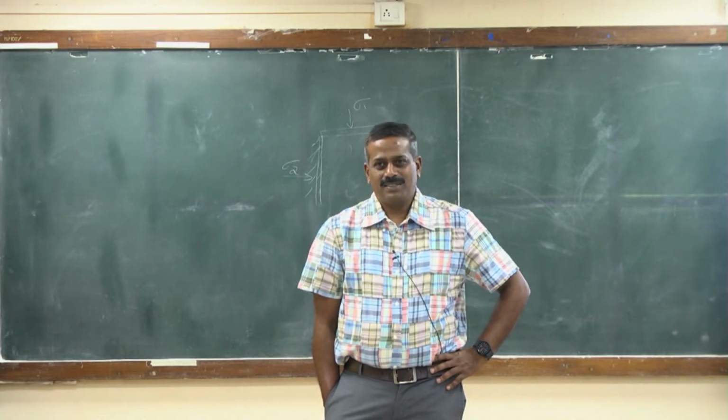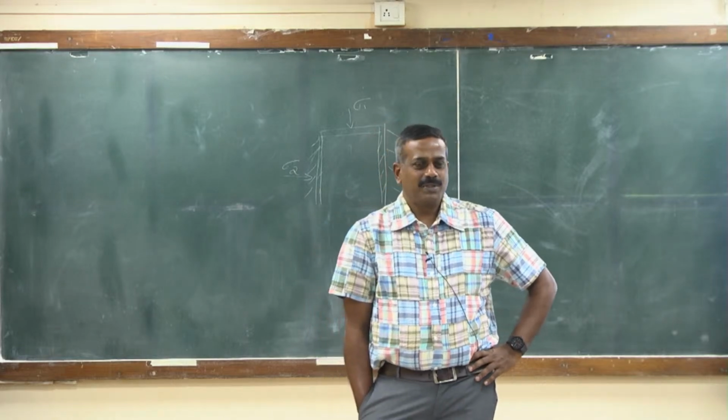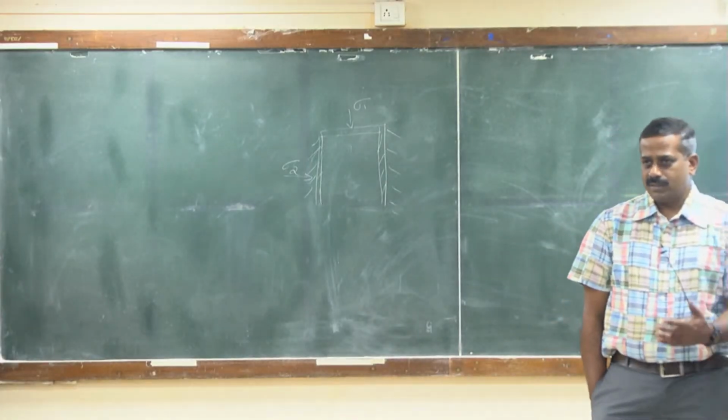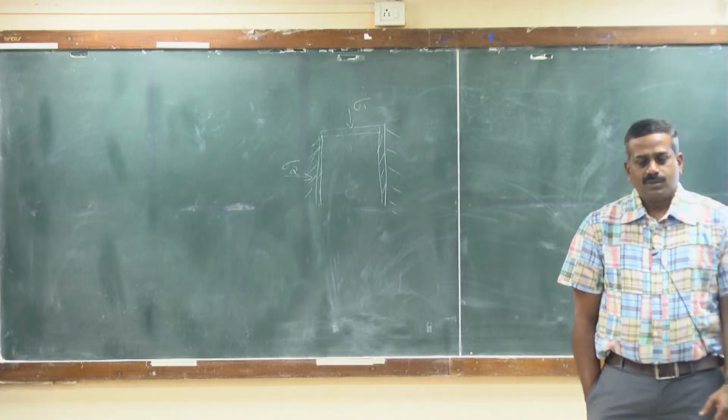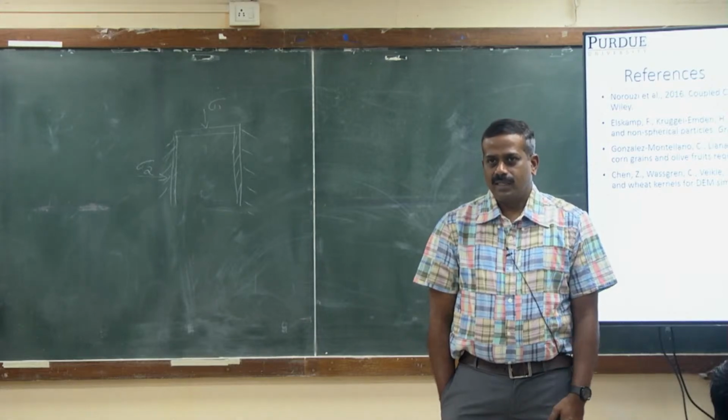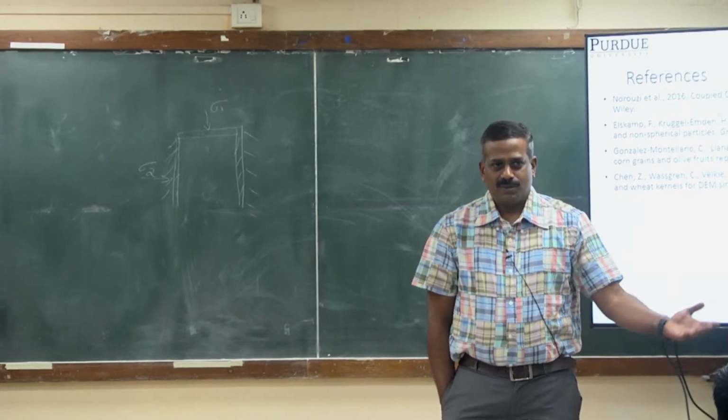Okay, so I will give the answer. We don't measure. It's very difficult to measure for small materials, so we assume. When you are doing modeling, you simulate with a range of restitution coefficient values, and through experimental validation, you find the appropriate coefficient of restitution. For larger materials too, we talked about lots of challenges for measuring coefficient of restitution. So most simulations, when you see those papers, they don't measure. They do some calibration of parameters.